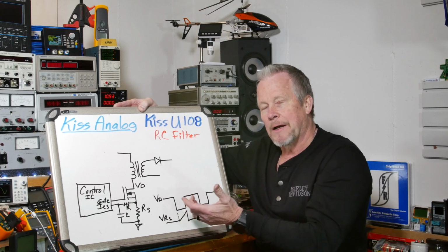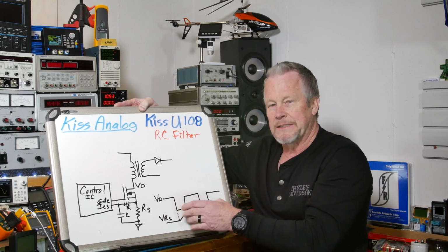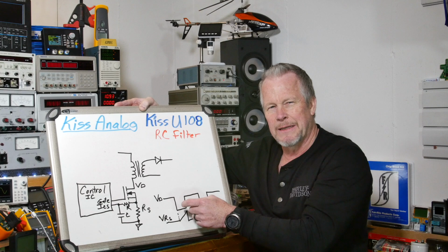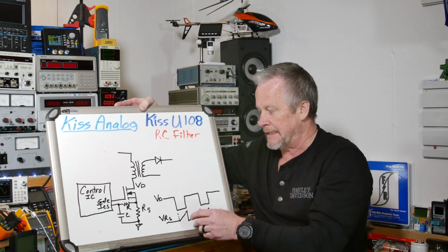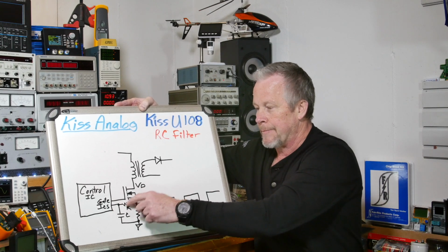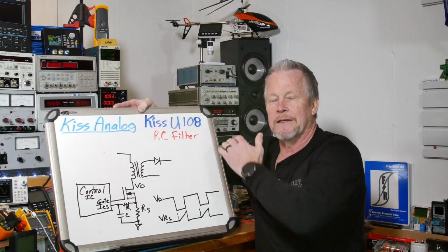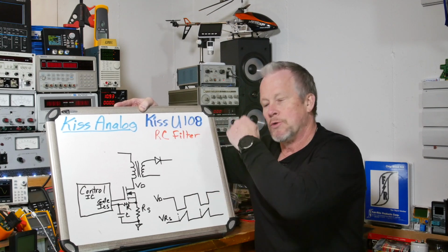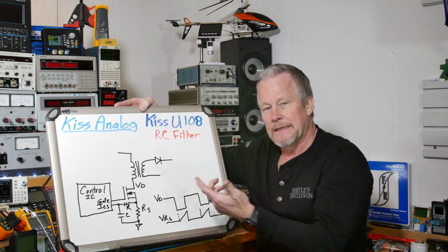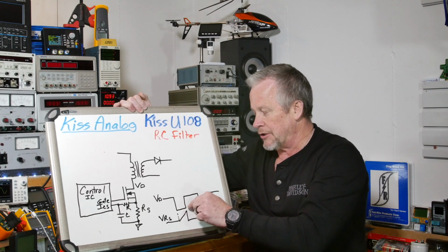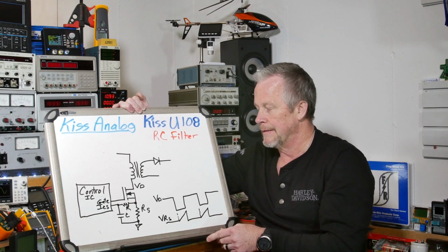Let's say this is running at 100 kilohertz, and you've got at least a microsecond of on time. Well, then you say, okay, 10% of that, 100 nanoseconds. I could put a filter for 100 nanoseconds so that the first couple of time constants smooths off this spike, basically kills it, and that way it doesn't trip my thing. Then time goes on, it charges up, and it finally hits the trip limit and trips where it's supposed to.